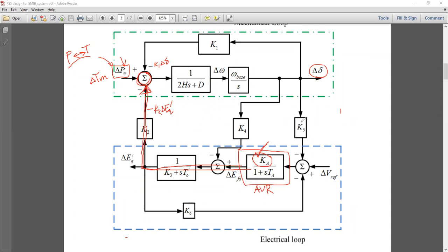So that's why we are trying to look into the actual cause of this instability. The signal coming from the effect of Ka is fed through this path into the summing junction in the form of torque. That is actually creating some lag. We'll calculate the lag later on, but this is the basic idea that we are trying to explain here.